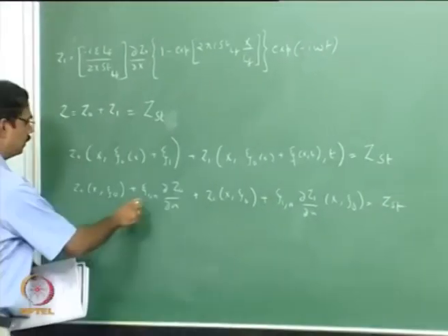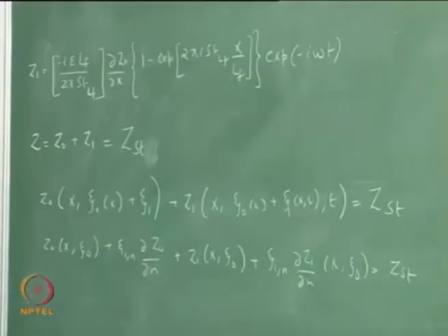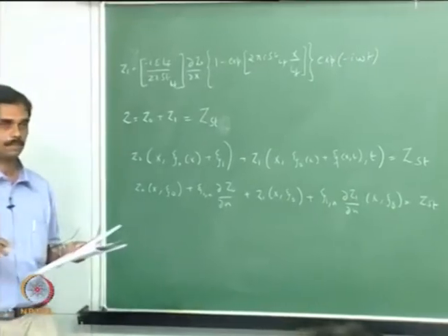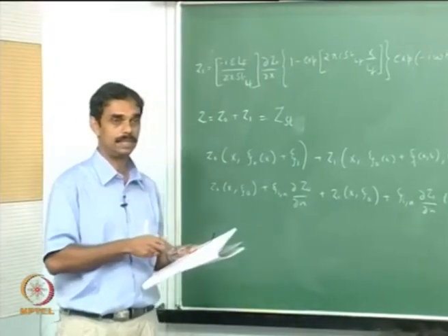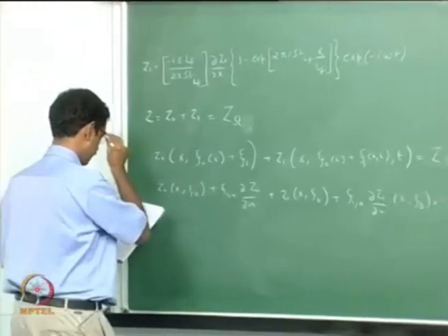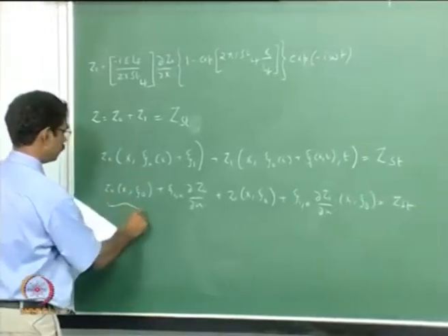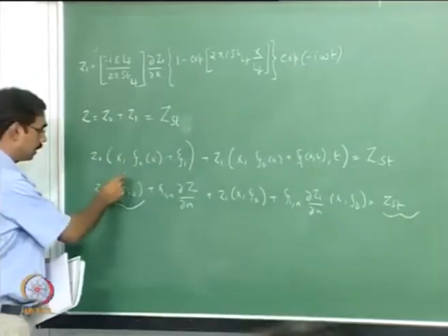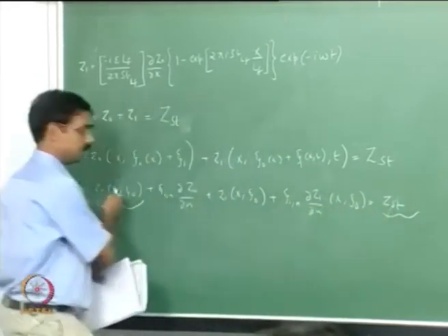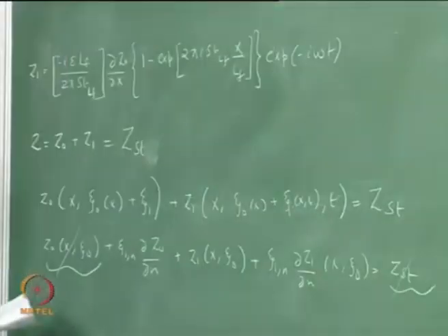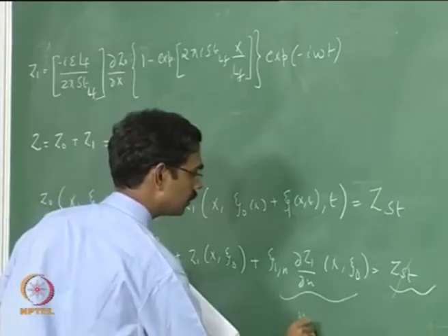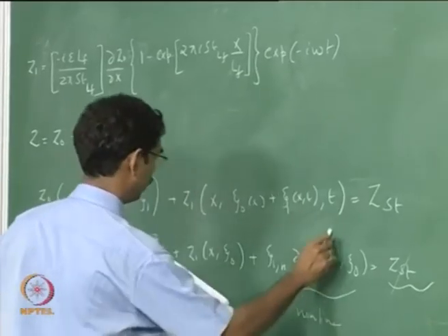So psi, we are measuring the flame position as a normal from the steady flame. That is actually quite convenient because otherwise the flame angle will change dramatically towards the flame tip, and this is same as this. So you can cancel because this comes from the steady equation also, and this term is non-linear, so we can drop that.